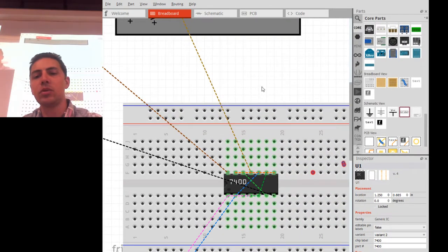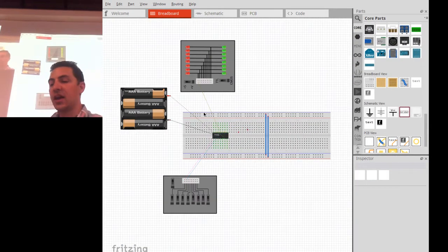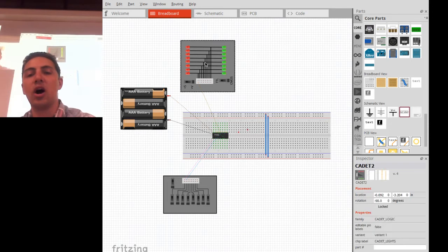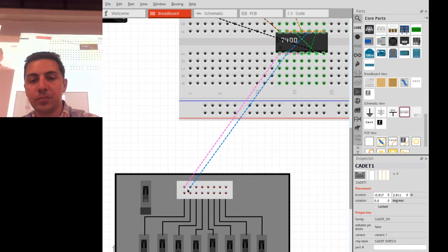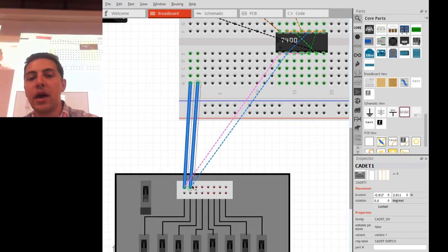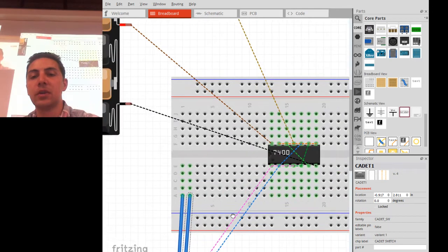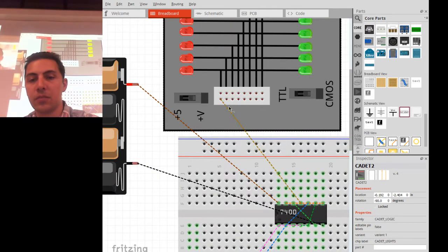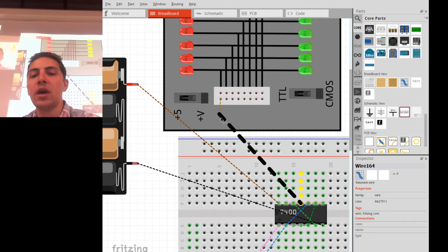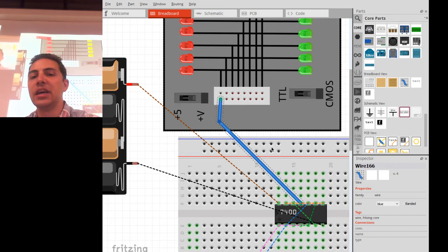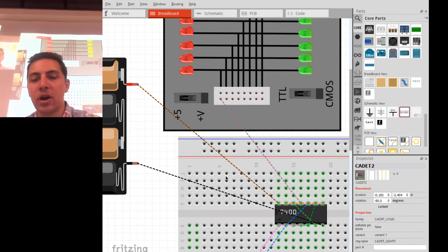All right, so the first thing we're gonna do is take into account that we don't wanna wire all of these components directly onto the board. So I'm just gonna grab someplace off on the side of the board and connect them to the switches. I'm gonna do the same thing over here. Oop. This time I actually clicked on the dashed line. You notice how it became bold very fast? As soon as I let go of the mouse, it's put a wire in there. That's not what I want to do. So I'm going to just drag that wire in there.